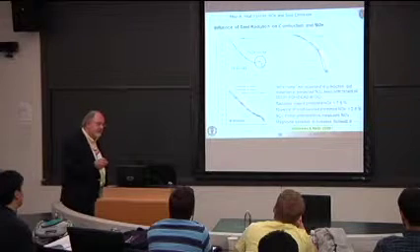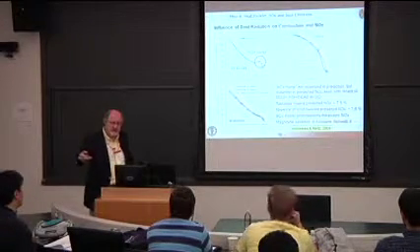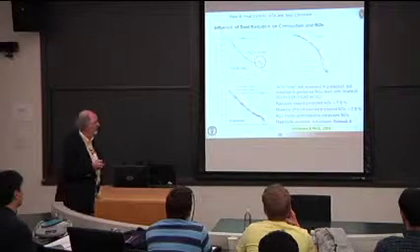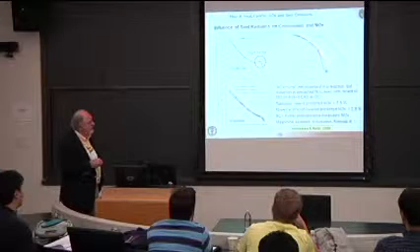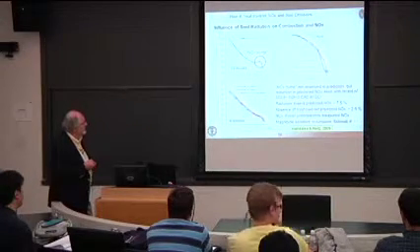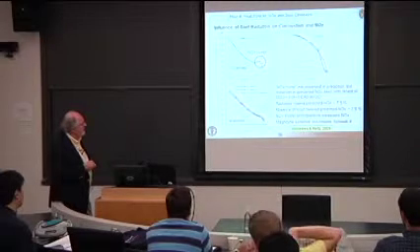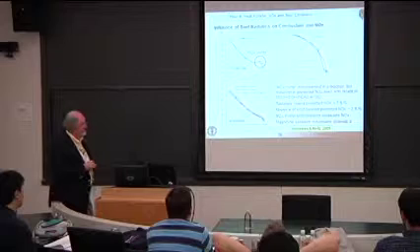So that means that the radiation associated with the soot is no longer important. Now remember I said how the radiation actually lowers the gas temperatures because you're essentially sending that energy to the wall. So with a lower gas temperature, you would expect to see a reduction in NOx. And so his argument was that if you don't have radiation, you're going to see an increase in NOx. And that explains this bump.